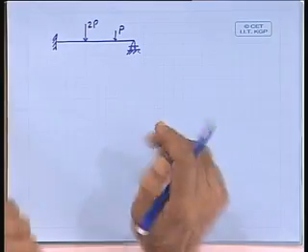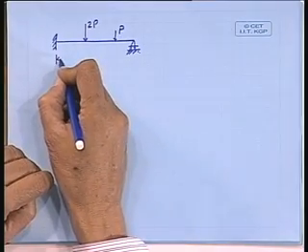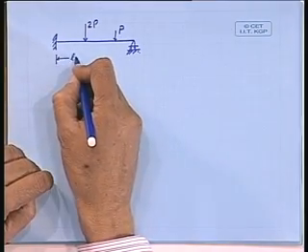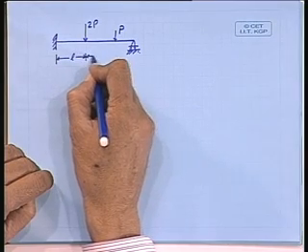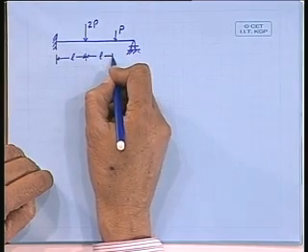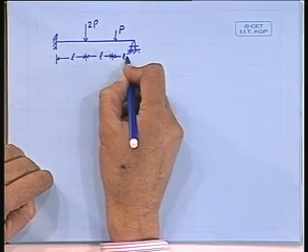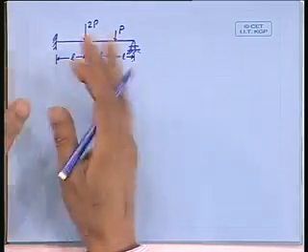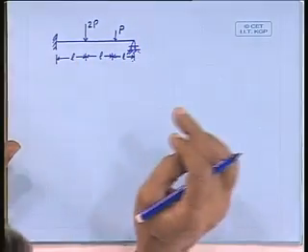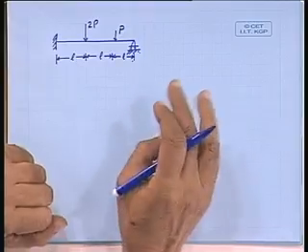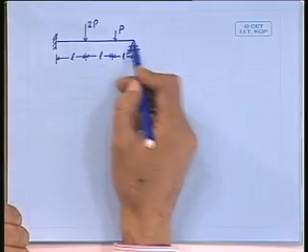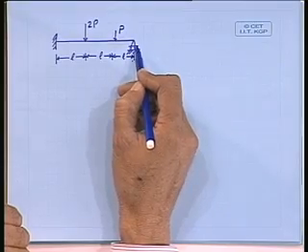Right, and let me make this span L in this fashion so that I can have a simple calculation. Now we have seen that 3 hinges are required for the collapse mechanism, and the way it collapses is known as the mechanism. Now in this case we can start from here. There is a physical hinge provided here.